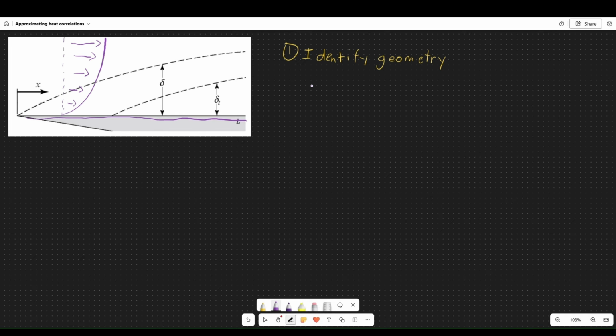And so you see this velocity profile, but we need to find a certain way to describe this behavior so that we can give an overall h, because the velocity is changing, and we want to know, okay, how much heat transfer is this fluid taking with it. And so usually when you have things like this, you'll have this boundary that you call a film. And so what we want to do is basically discover, okay, what is the temperature of that film, and then use that in order to calculate other parameters that will allow us to finally find H. And so let's get started on that.